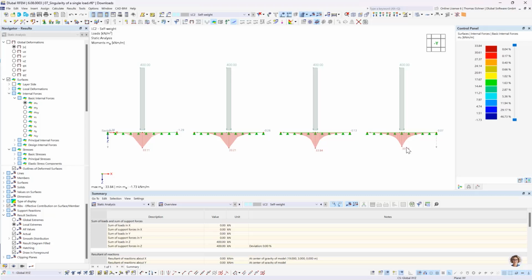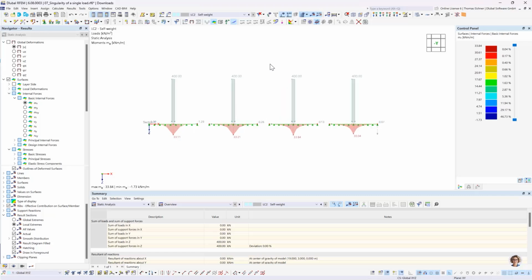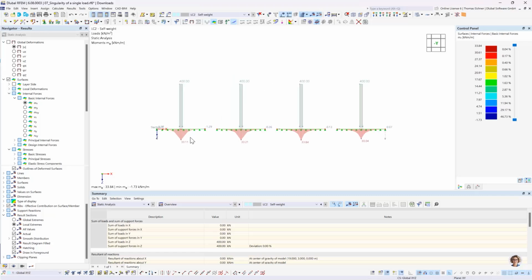This one is a bit smaller than the rest now. We have 30. I think with the smoothing rate, we had roundabout 31, maybe here 28. And yes, that's quite cool. One other thing, of course, you could also combine those two variants. So we could use this result now and also smooth it over a certain range. So that's one possibility, or two possibilities, to counteract singularities.